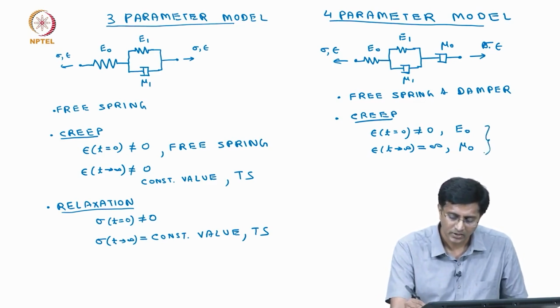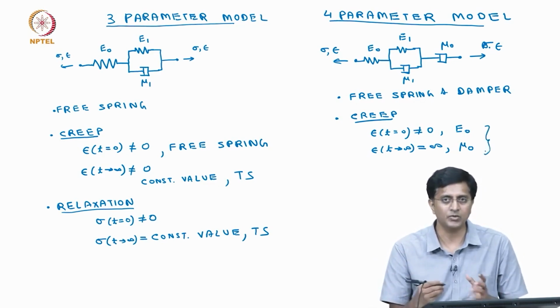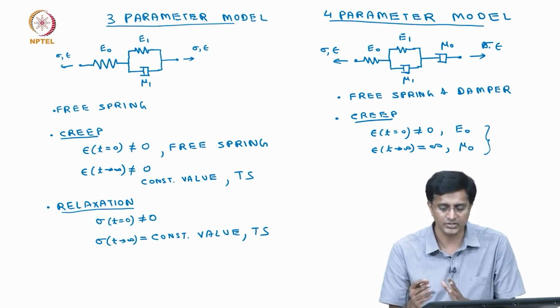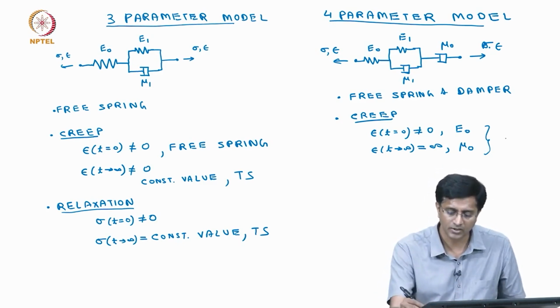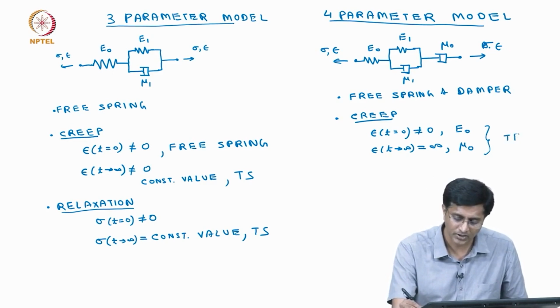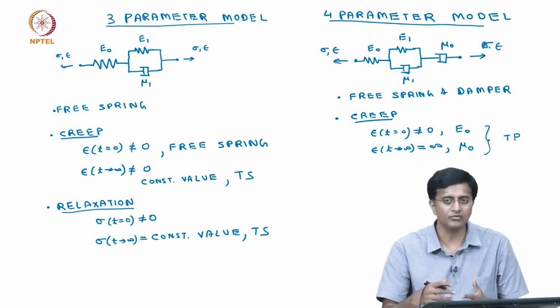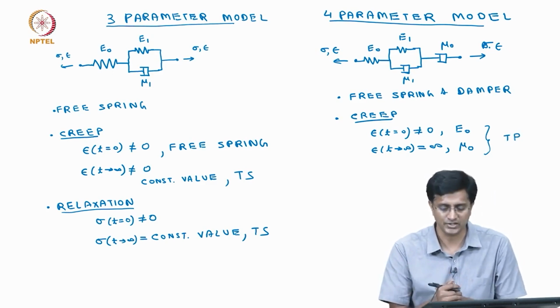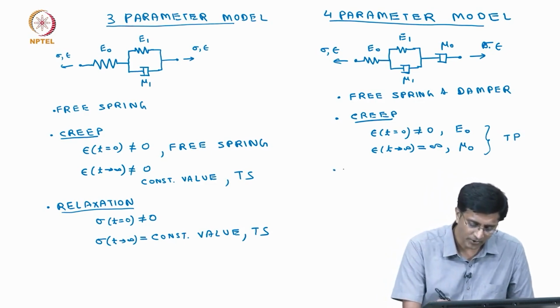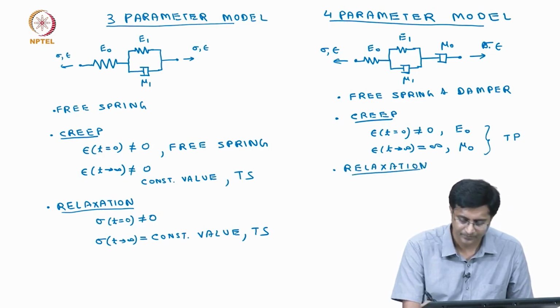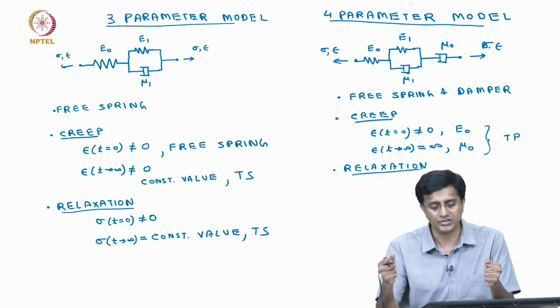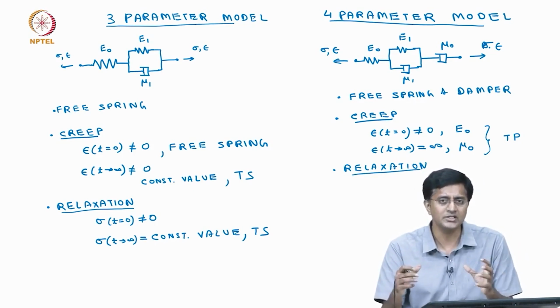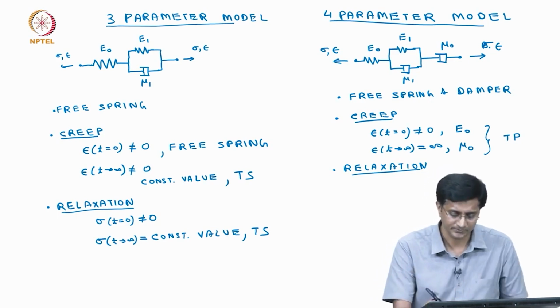And we are saying this plays well with a thermoplastic or a thermoset. We have seen that this plays well with a thermoplast, because in a thermoplast if we wait long we see infinite strains. Now moving into the relaxation behavior. Now if we apply a constant strain, that instantaneous strain is taken by the free spring.